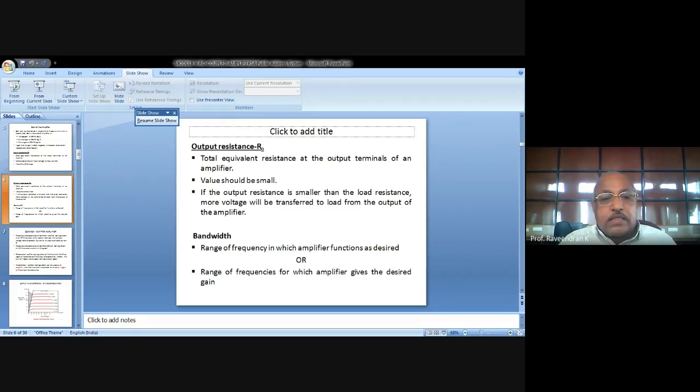And I told you, since the resistance capacitance network is used to couple between the multi stages of the amplifier, if you want to amplify the signal further with another stage, second stage of amplification or third stage of amplification, then what do you have to do? You give the first stage amplifier output to the input of the second stage amplifier. Output of the second stage amplifier is given to the input of the third stage amplifier. But in what way do you have to give? You have to connect the first stage and second stage through a coupling capacitor.